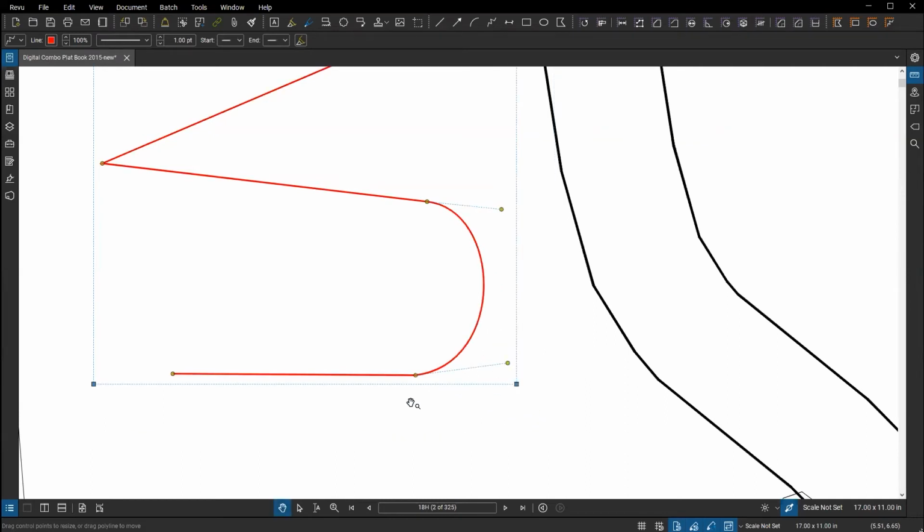So if I have to match some weird curving gutter path to go around, or a roundabout, trying to go through and trace appropriately, that might be a means to go if you want that curve to map the design a bit more closely. And this can be done also on measurement tools. So if you have a poly length, and you have some entire length of some curving gutter, with curves and twists and turns inside of that, you can map that path and get the overall linear distance of that, even around the curve.